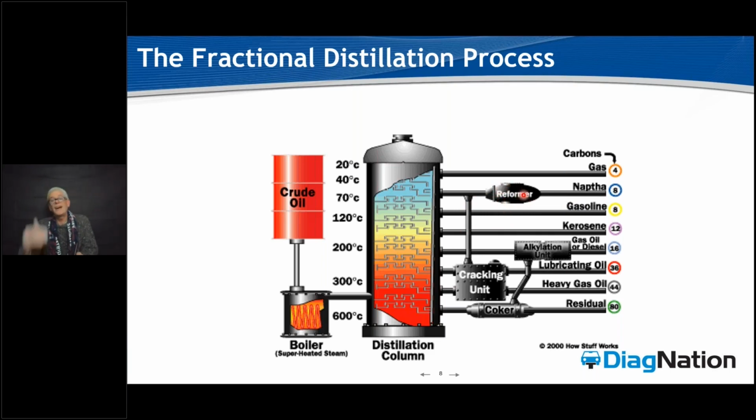Now, this is where the higher elements, the more volatile, high evaporative or lighter elements of that fuel are then blended with the heavier coked cracked base, okay? So that at the end of production here, what we've ended up with, if we draw a line from here, considering this pipe, and here, considering we're in the gas and naphtha band, is that we're building an average manufactured 8 carbon chain gasoline.